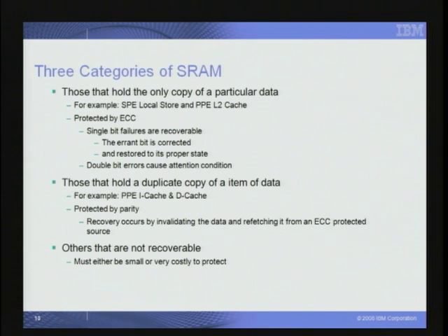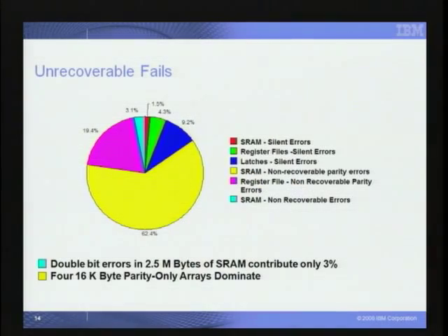And then there's a few others on the chip that are just not recoverable, and so we had hoped when we designed it that they were either too small to matter, or when we looked into the cost of building protection circuits for them, we felt like it was damaging to the notion that we'd be a consumer electronics device. So that ends up with sort of an error breakdown as to why we expect PowerXCell 8i to fail.